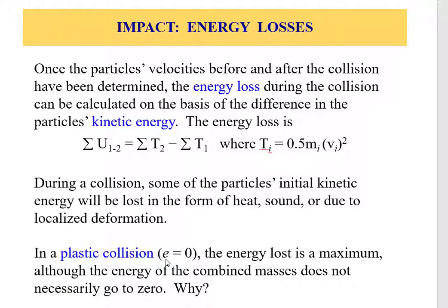So talking about losses, if you want to compute the energy losses during the collision, it's simply estimating the energy difference after the impact as compared to the total energy before the impact, which means we're talking only about the kinetic energy losses. We assume all these impacts happen on a plane, not vertical, in a planar coordinate system where the potential energy is not taken into consideration.